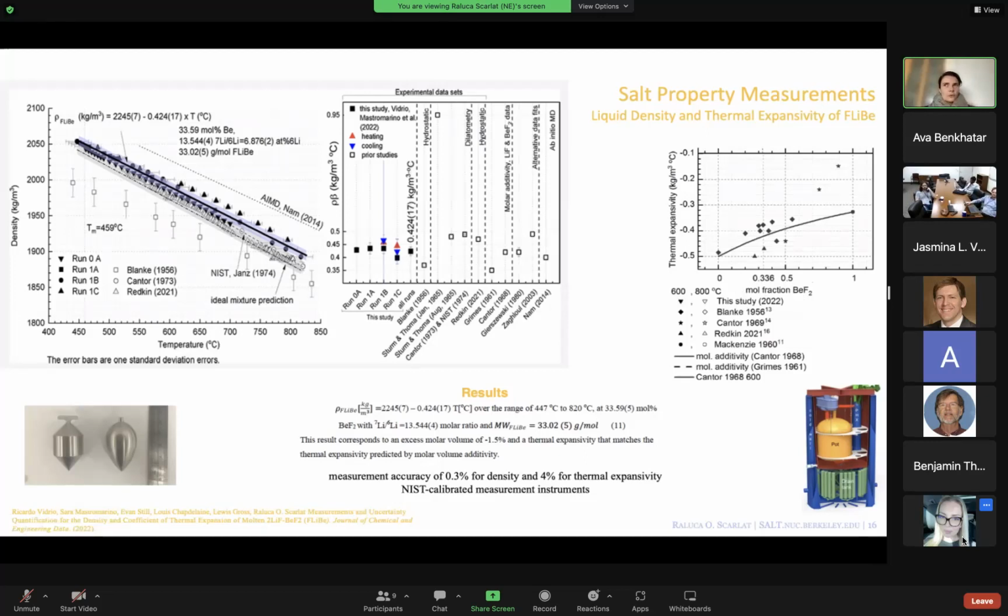If you're on a liquid fuel, so if it's sodium fluoride, sodium chloride, uranium chloride, then obviously the mass difference, the density, the molar volume difference is big there between the two constituents. So 0.3 accuracy on density would give you a sub-mole % accuracy on composition, which is pretty helpful. Right. Okay, thanks. Yeah, so it's condition dependent, but those numbers seem great. Yeah, but it's a question of can we push the applicability of density measurements towards inferring composition is what we're asking here.